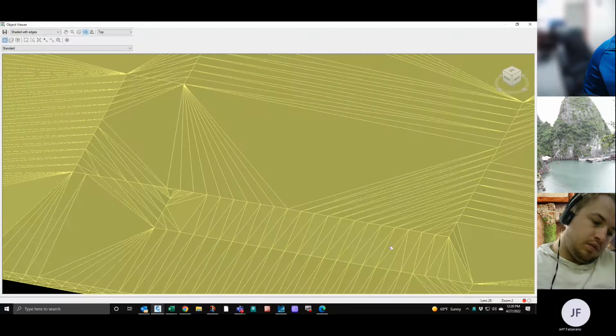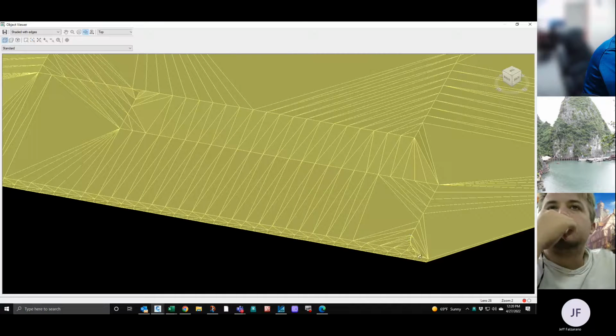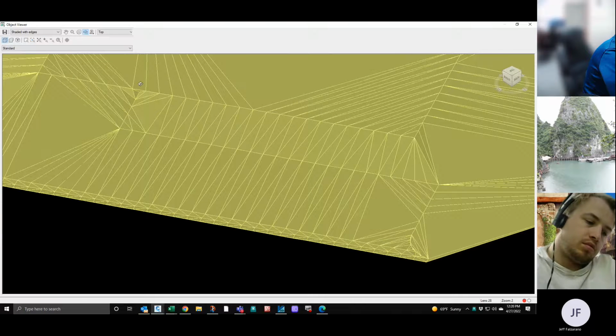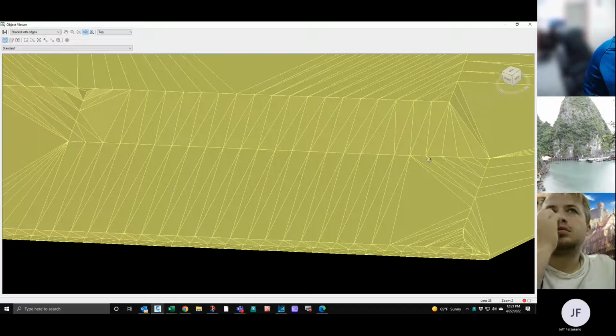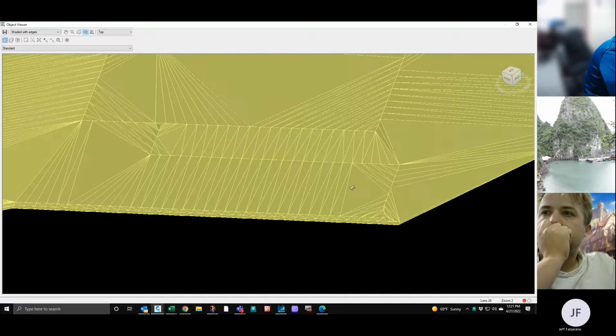Here's that flow line, and then we go up to the building. And then there's an elevation bust right there, just because this point might be so much lower or higher than that point, which is normal. And then we'll just take a feature line at this end and go down and tie it into the other end of the sidewalk.